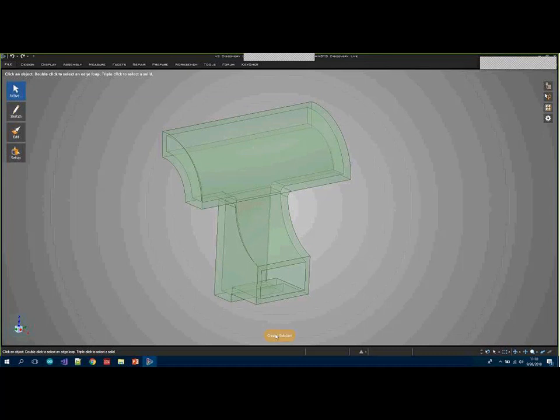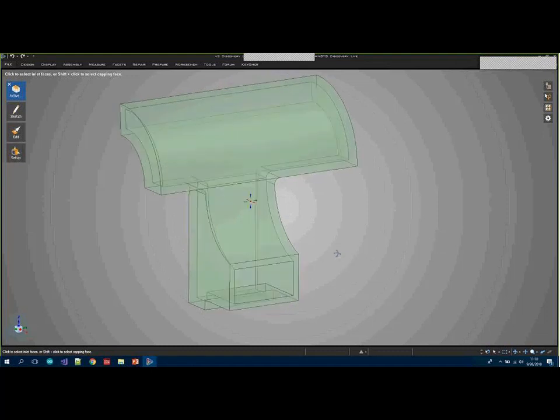So down here at the center, we have a button that says Create Solution. We'll click here, and you can see the various different solutions that are available to you, which I mentioned earlier. We have thermal, we have fluid, structural, and modal. In this case, we're interested in fluid behavior. The object or the fluid itself is going to be air. And so I'm going to select to create a fluid volume, and here I'm going to select internal flow. A little bit later, we'll cover external flow. But for right now, we want to see what's happening inside of this HVAC system.